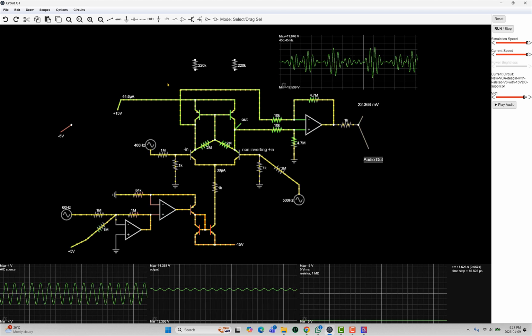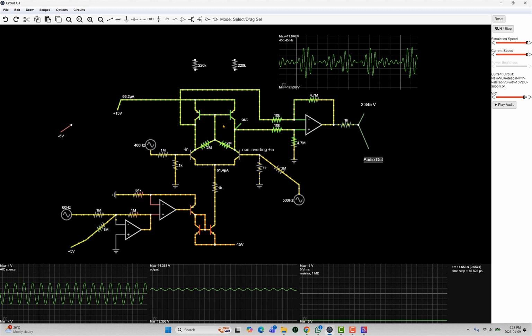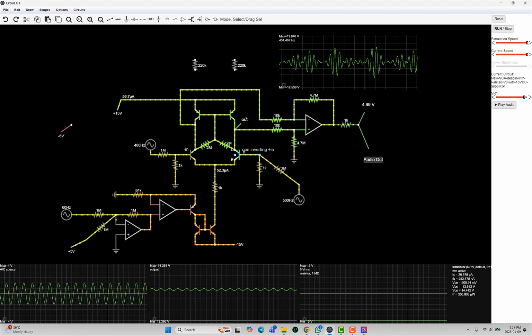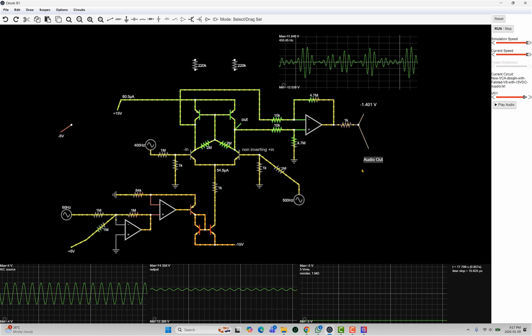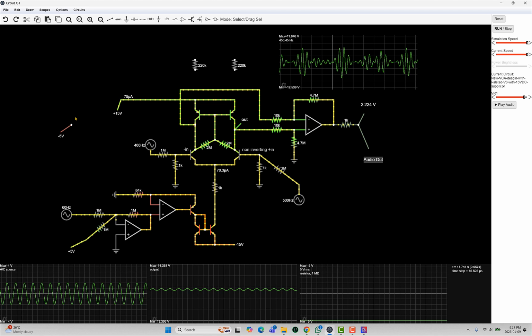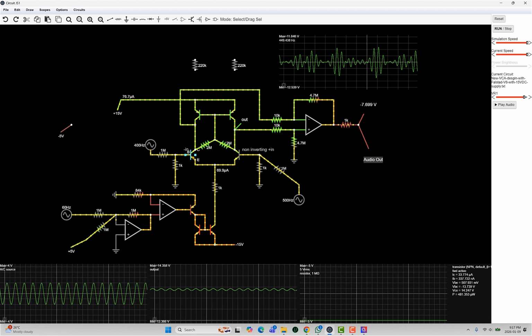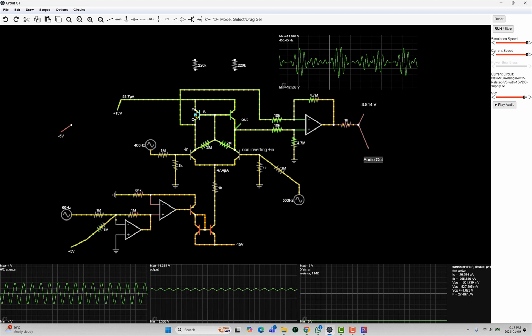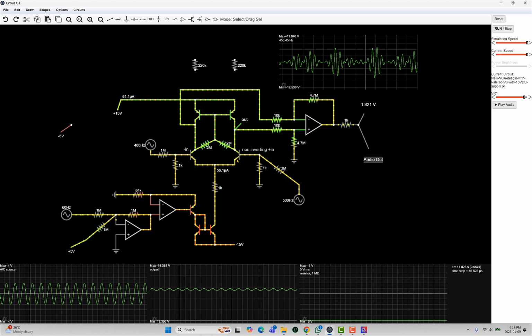The range is really linear all the way through from 0 to 10 volts. So the gain of the amp is really nice. But that's if maybe the parts have to be, I don't know how accurate they have to be, but it'd be interesting to get some feedback on that if anyone gets a chance to build it. I think these are just 2N3904s and 3906s in the simulator, but the simulator uses perfectly matched ones, right?